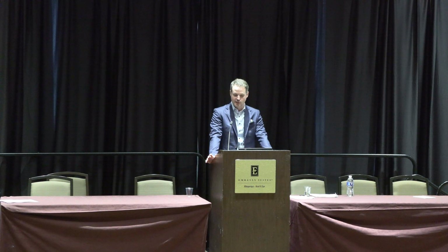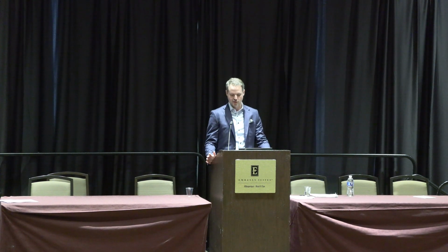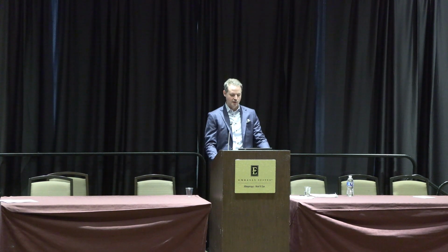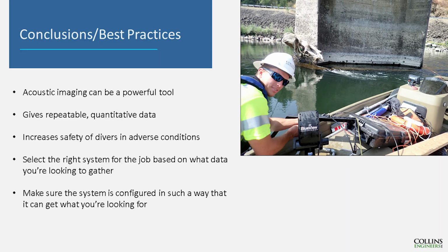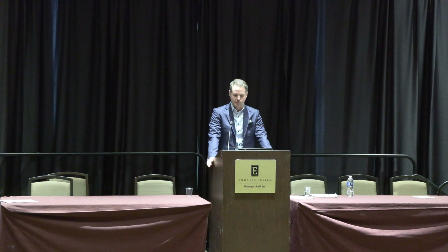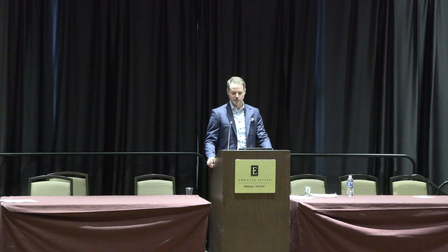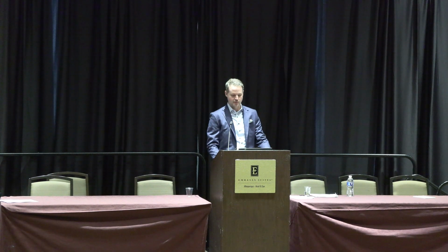You want to select the right system for the job based on what data you're looking for. There are many different types of sonar, and this one might not be the best for every situation. I didn't cover some of the other ones, but depending on the situation, a single beam or a 2D sonar system might be better, which we use a lot depending on what's going on. And you want to make sure that the system is configured in such a way that it can get what you're looking for. If we had gone out there with a boat-mounted or tripod-mounted configuration, we never would have been able to scan the features that were close to the channel bottom that we were looking for.